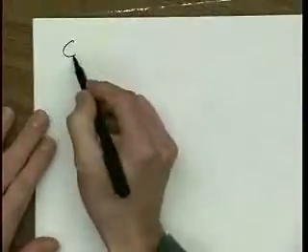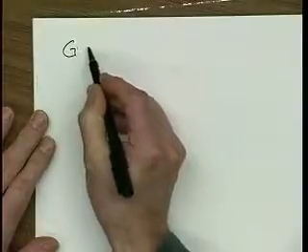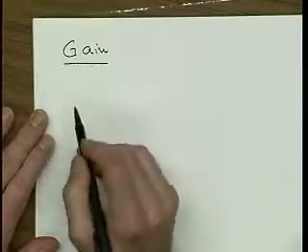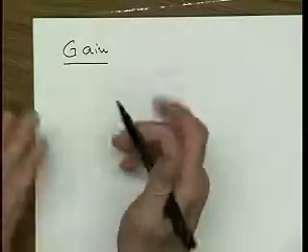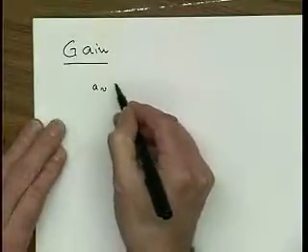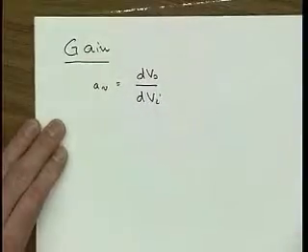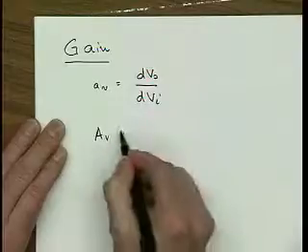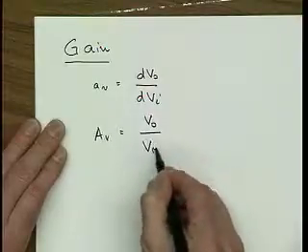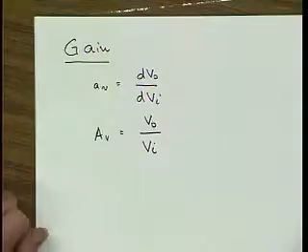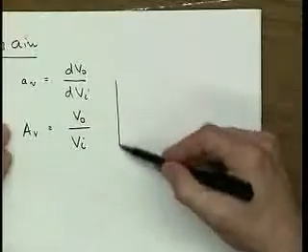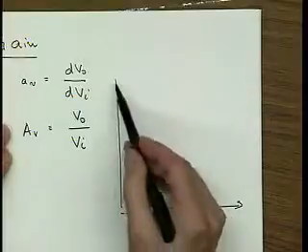Okay. Then one other thing that I would like to quickly go over is that last time I got a few questions about gain. This is still concerning lecture 3, gain. We really have two definitions of gain. One of them is the small signal gain, AV equals dVout over dVi. And the other one is the large signal gain, and that would be Vout over Vi. Okay? And I had plotted these two gains for a common source stage, and they looked something like that here.